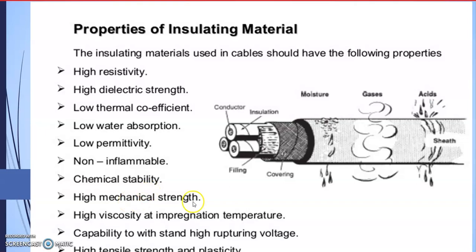It should have high mechanical strength. When you are using it in the atmosphere, these cables will pass over a long distance, or underground also. So what will be the weight coming on this cable underground? Mechanical strength has to be large. Otherwise, due to stone layers, soil layers, and the weight of the ground material, it will start wear and tear, damaging and scratching some parts. I have told you, a small scratch will also lead to breakdown. A small dust particle will lead to the breakdown. So mechanical strength also should be very large, and due to this, underground cables are very costly.